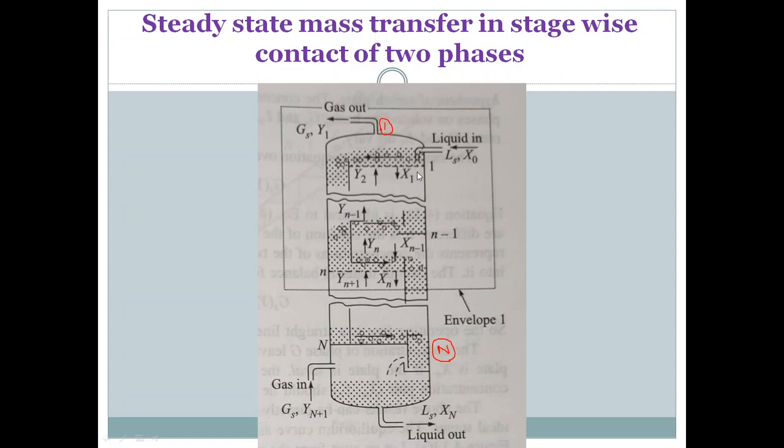Or I made some arrangement, which I will discuss later, so that the holes can be modified such that only gas can come from the bottom to top, but no liquid comes down. So liquid will come only when there is overflow. So if I make this, that means it is a mixer. So here I am making one stage, and if I allow some time to mix them, then it will reach equilibrium. So I will make one stage, stage 1.